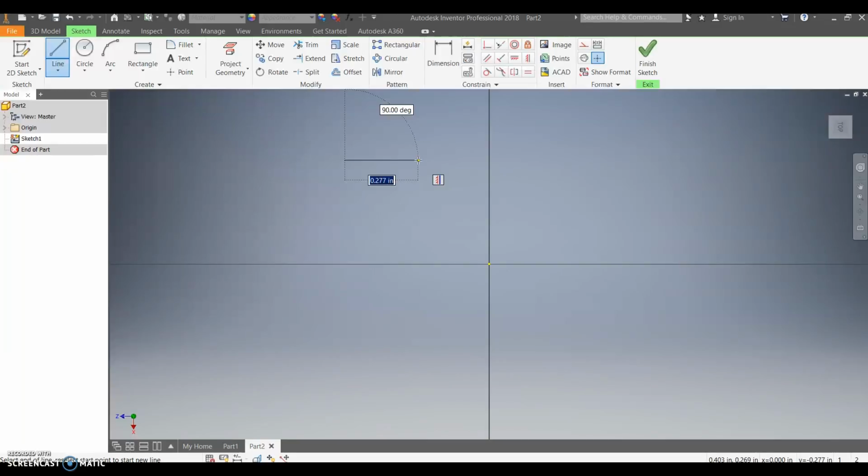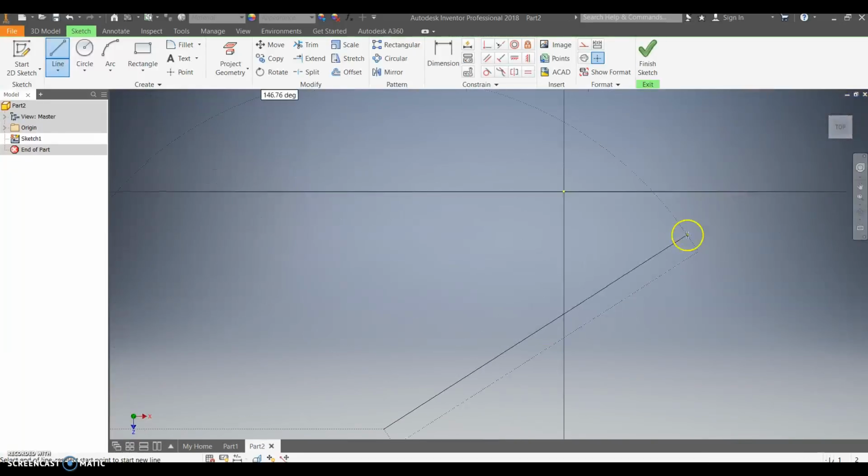And if you look on the right hand side, there's that little box that has a constraint sign on it. It shows that it is drawing that as vertical. Now it's vertical because if you look in the top right hand corner of the screen, it'll say top. Well, that top is actually rotated. So if I was to turn this like this, and I escape this, and I go back to line, and I draw the same line again, it's now showing it as horizontal.